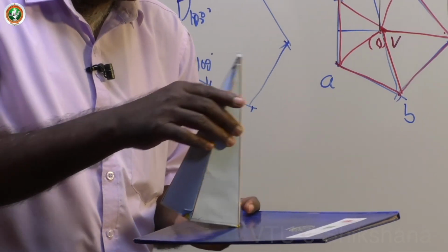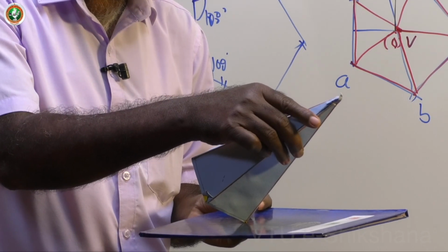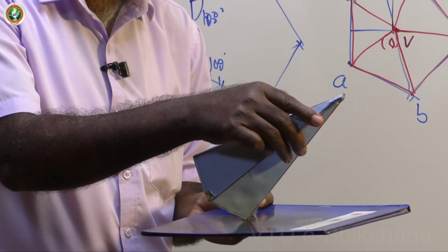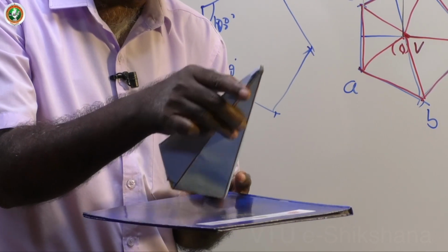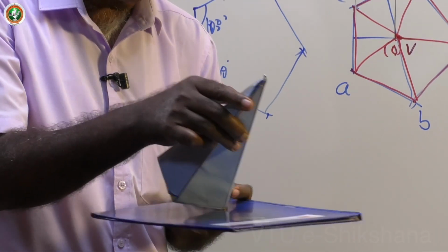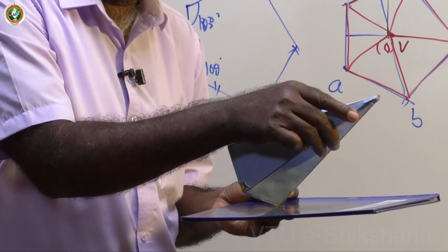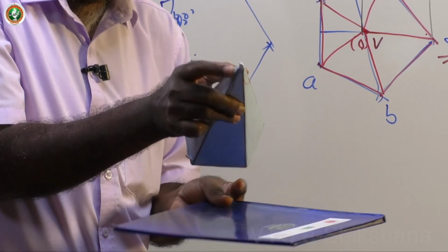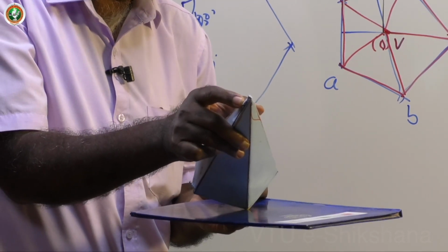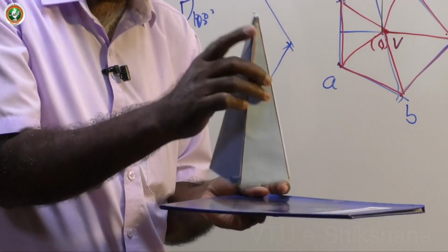Then only once you incline this, the axis will be inclined to only HP, and these two base sides containing the corner and HP make equal inclination with HP as well as VP in this condition. But once you give inclination to VP, the inclination to VP changes, but these two will have same inclination with HP, equal inclination with HP. That is the basic condition.